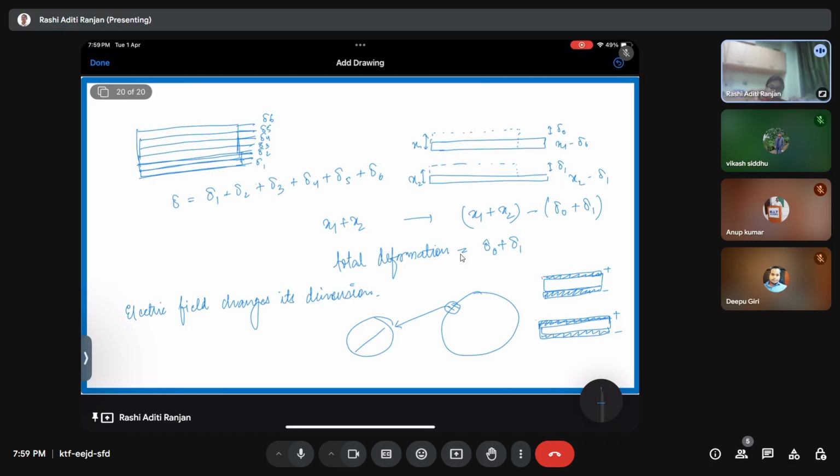Likewise, I can use electroactive polymers for that case, because in that case we'll have a much wider application, because here I can change the stiffness of my system. This behaves in a viscoelastic way. So the viscoelasticity also changes depending upon the deformation, and hence if the deformation changes, then it is going to show a change in the properties, which could be helpful for me in order to balance out the large amount of residual vibration, large amplitudes and frequency. Okay, I hope this is clear.